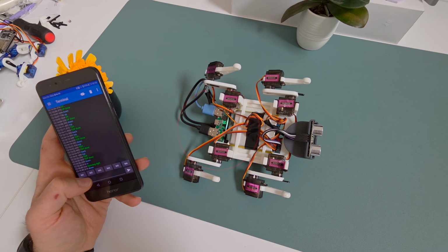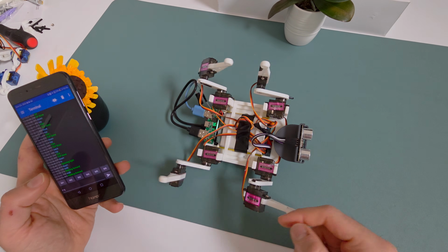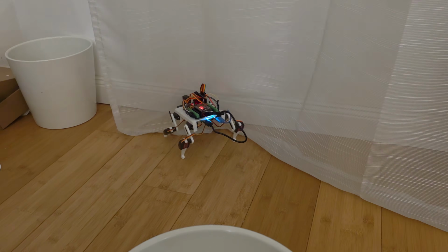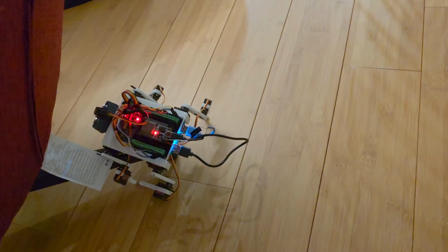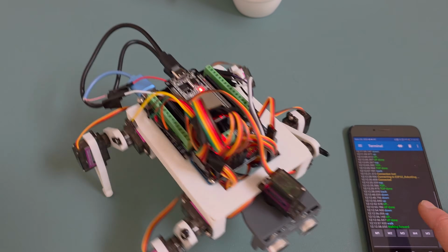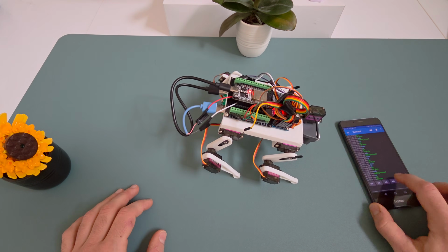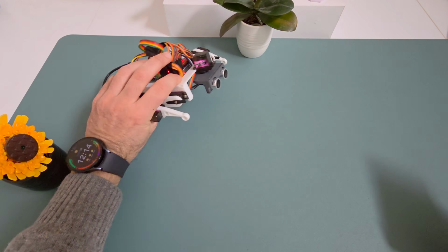The fix? I leveraged the power bank's dual output design. I ran one dedicated line to the servos and a completely separate one to the ESP32. Instant stability. Albert is a testament to what you can do with a $50 budget, some 3D printed parts, and the help of AI to bridge the math gap. He's my new favorite desk companion, and he's ready for you to build him.